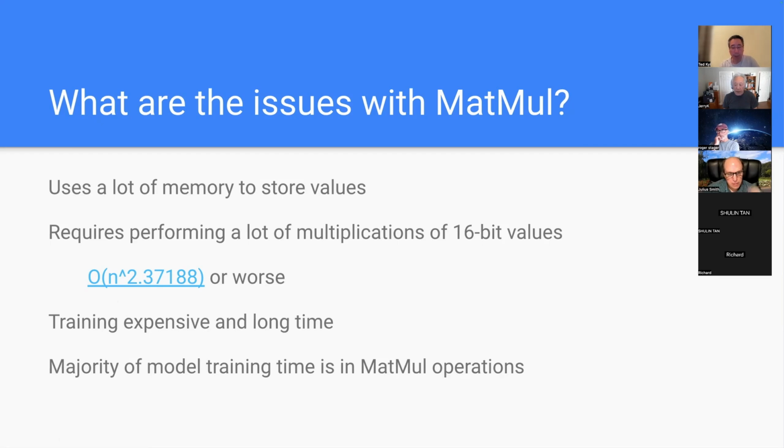Okay. A very quick comment. Yeah, go ahead. So it's a lot of operations, but in particular, of the operations, it's the multiplies, not the adds, that are expensive. Mm-hmm. And multiplying two 16-bit integers would be even slightly less expensive. But multiplying two floating point numbers is extremely expensive. And so that's the part that people would like to avoid. Is that because of the mantissa hanging off the end there?